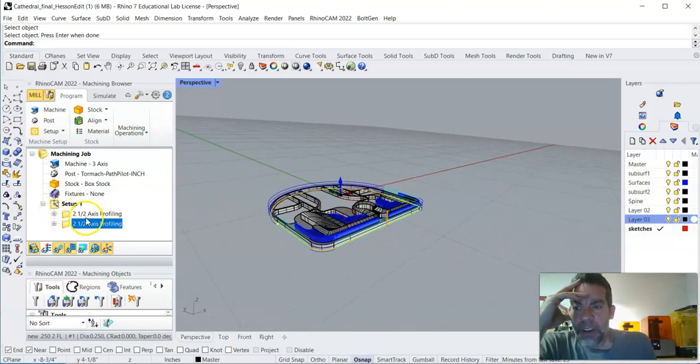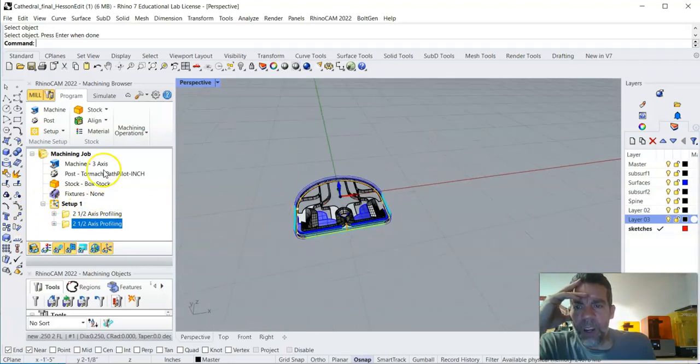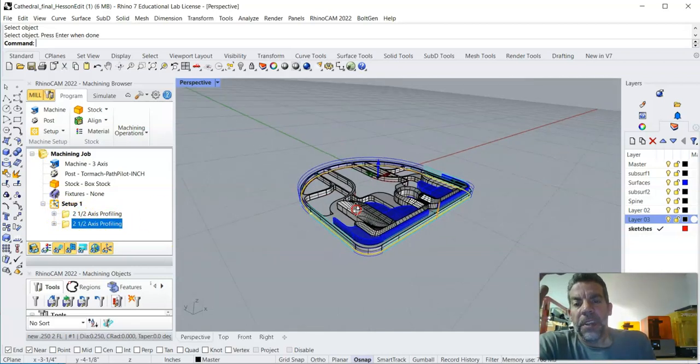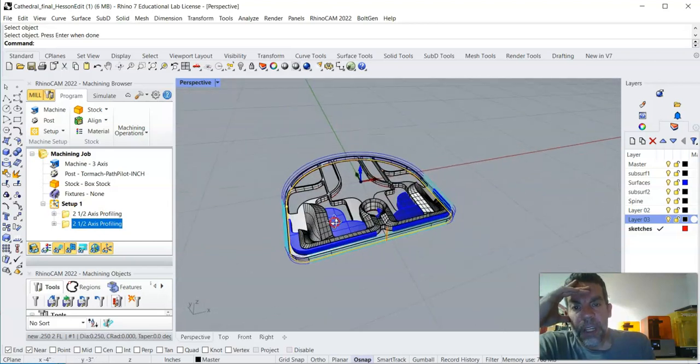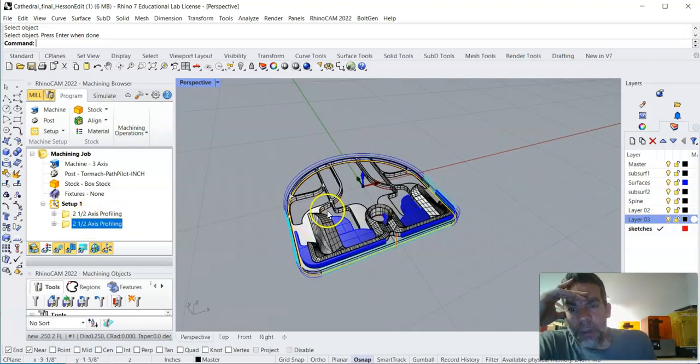So we're going to fill in all our operations in between here. Okay. All right. So this will be our first, and then if we wanted to, we could stop the machine, remove those windows by X-Acto knifing the bridges, pop those out, and then we can continue milling. All right. Okay, so a couple things we could do now.